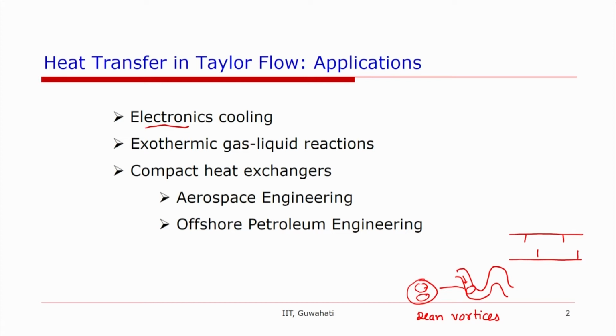Further on, if we want to increase the heat flux, for a single phase, liquid only flow, if the heat flux is increased at one point, it will start evaporating, and in that case we will have boiling in microchannels. So that becomes important.